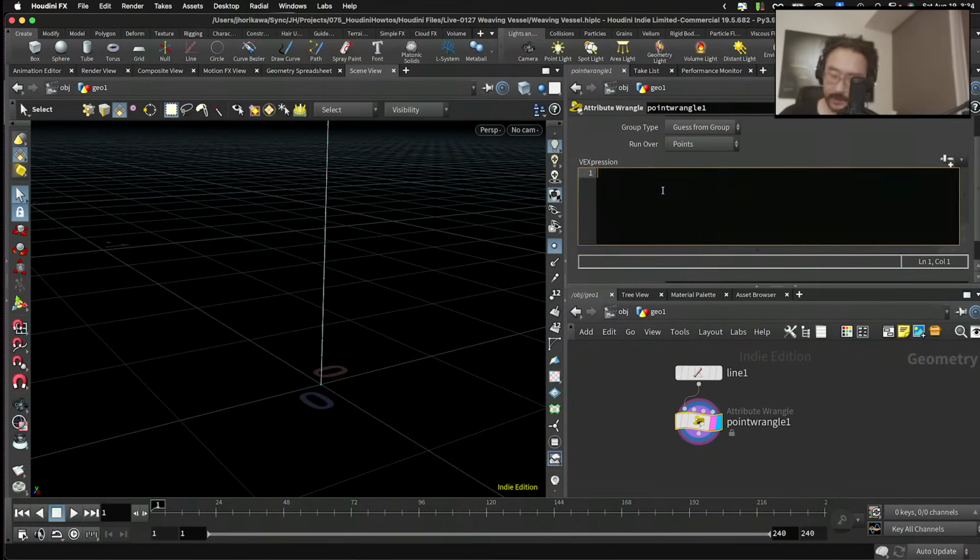you could use conditions by checking the point number and calculate the modulus. This percentage sign calculates the modulus, meaning it calculates the remainder. If you calculate the modulus with 2, you're getting the remainder when you divide pt num by 2. So if you divide 1 by 2, the remainder is 1. If you divide 2 by 2 or 4 by 2, the remainder is 0. So if you calculate the modulus, the only result you get is either 0 or 1.